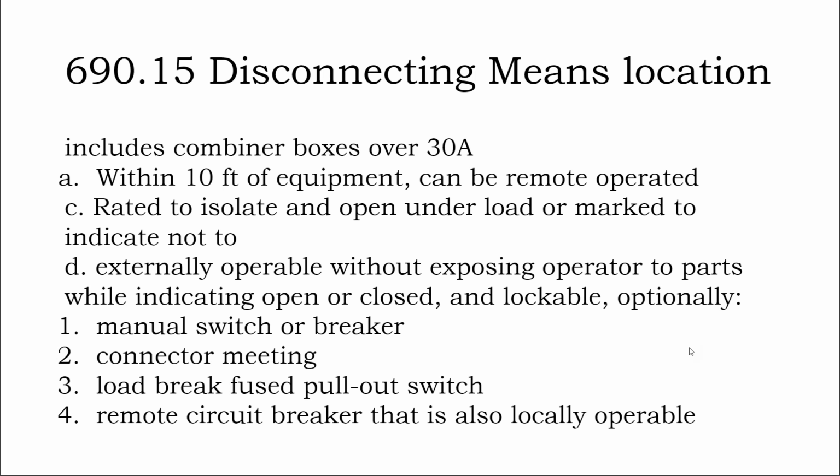I've usually regretted buying a 2-pole switch instead of a 3-pole switch to also disconnect the neutral, because you don't have to disconnect the neutral. You can just run it straight through. But then down the road, being able to disconnect the neutral is nice for truly off-grid systems where you don't want to backfeed. The utility's concerned about you backfeeding during a power outage.